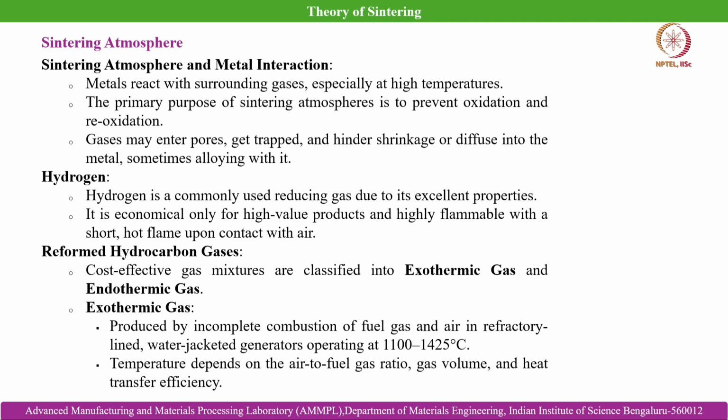These are the possible effects that can happen because of the gases present in the sintering chamber. Hence, if we do not desire these chemical reactions, then we generally use the gas cover as an inert environment to avoid oxidation, unless there is some special reason for achieving reactions in situ during sintering, which is not the case on most occasions.